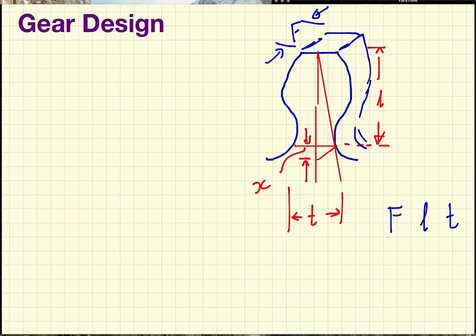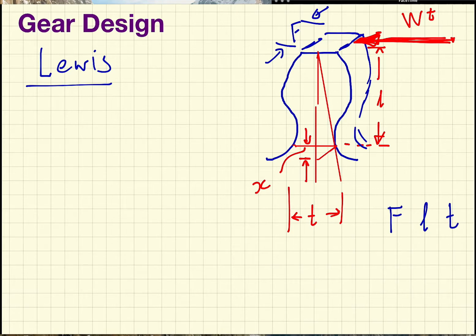So Lewis was the first one to propose a simple method to calculate the stresses on a tooth. If we look at the effect of power transmission, the transmitted force Wt is tangential, and it causes a moment about the base that is equal to Wt times L.